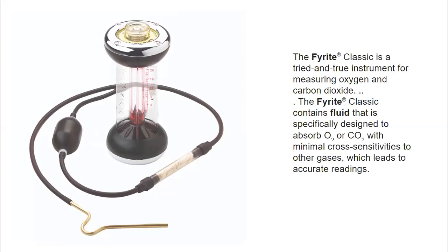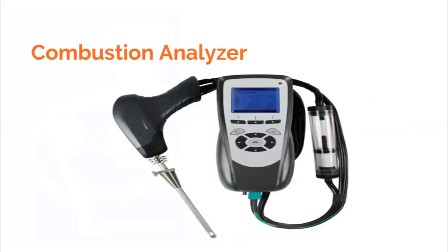The problem with the combustion analyzers is that not only the initial cost is high, but its calibration is also very costly. And you can imagine that, because you are experiencing very high temperatures, if it is not handled carefully, the running cost or the operating cost of the combustion analyzer is also too high.